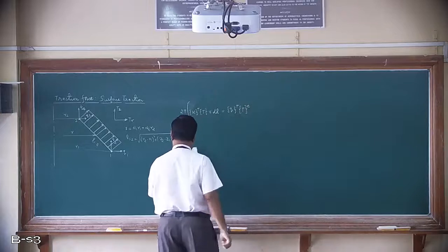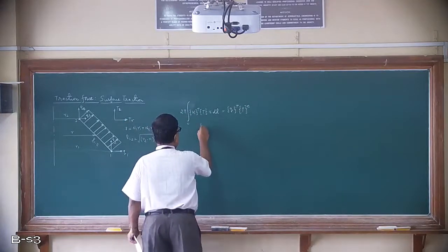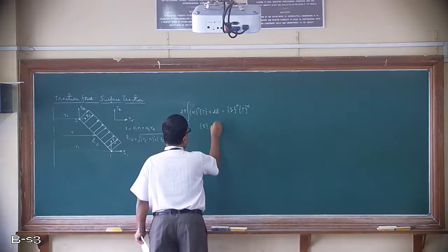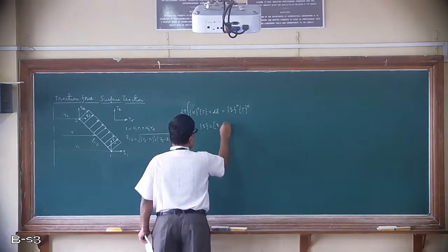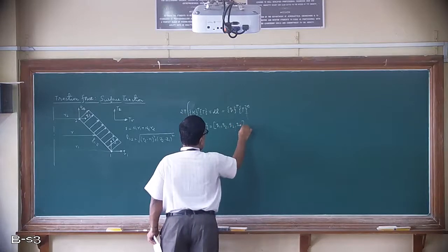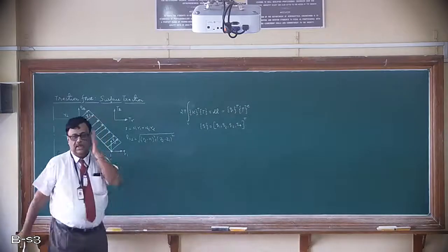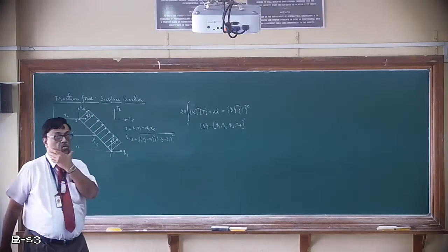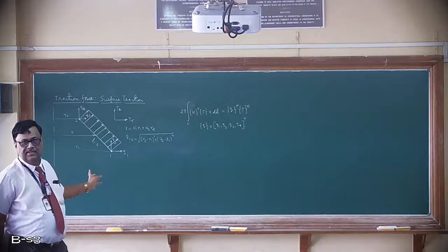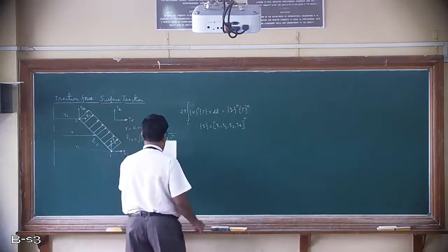This is, you can say, for every element. Of course, here your nodal displacement vector consists of only 4 displacements, Q1, Q2, Q3 and Q4 only. Q5 and Q6 are not coming into picture, since the traction is acting only along the edge 1, 2. Node 3 is remaining silent, so this will not be taken into account.